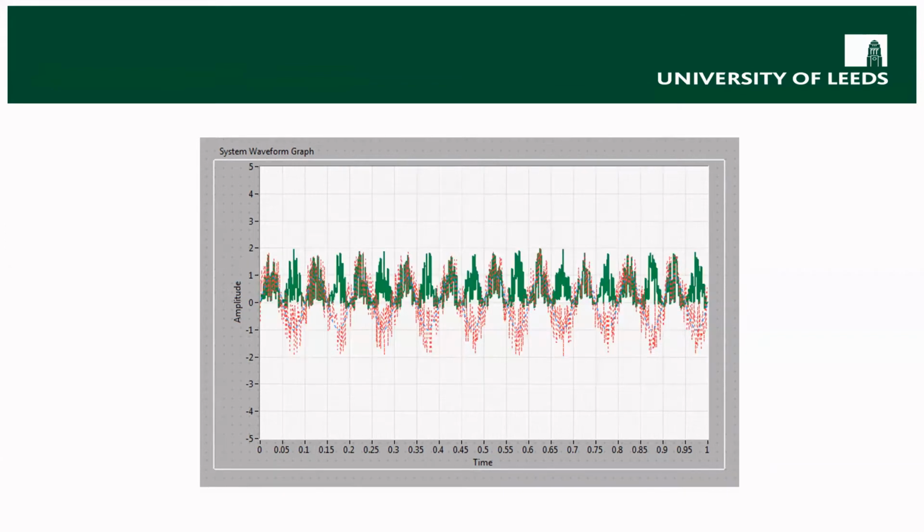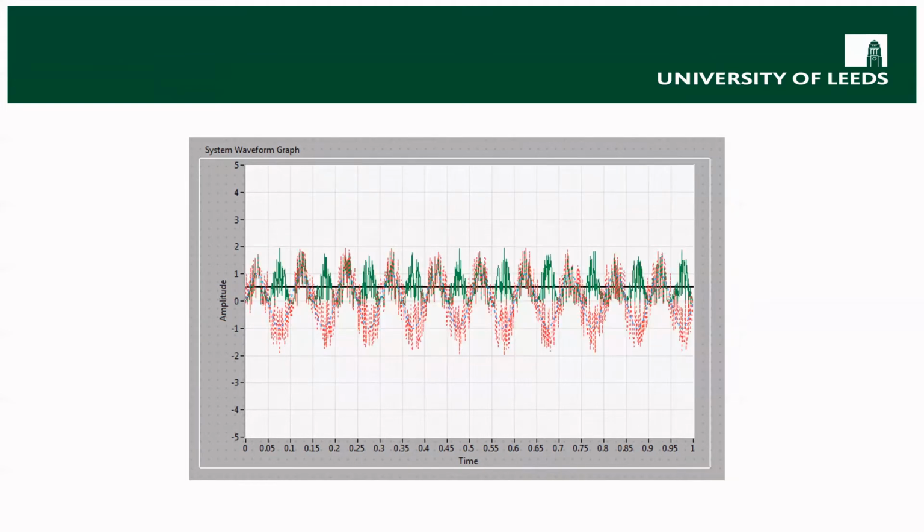So we now multiply them together, and we get the green signal. And what you see happening is that every time the response signal was going negative, our drive signal, the blue line, was also negative. So when you multiply them together, it flips over and becomes positive. And so we end up with a signal which is mainly going from 0 to some positive number. And if we then average that, we get a nice steady signal that actually turns out to be related to the size of the voltage. Okay, so can we actually go and show this?